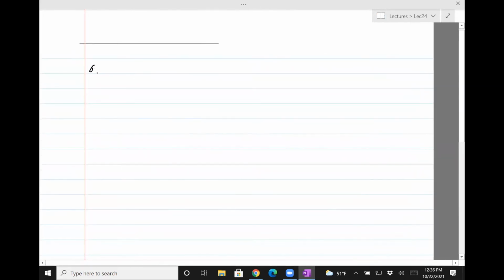Okay, so sigma x is My divided by I. As I said, M is F times 14. Y is the distance from the neutral axis. So for the shaft, the neutral axis is here, and maximum stress occurs at the top part.